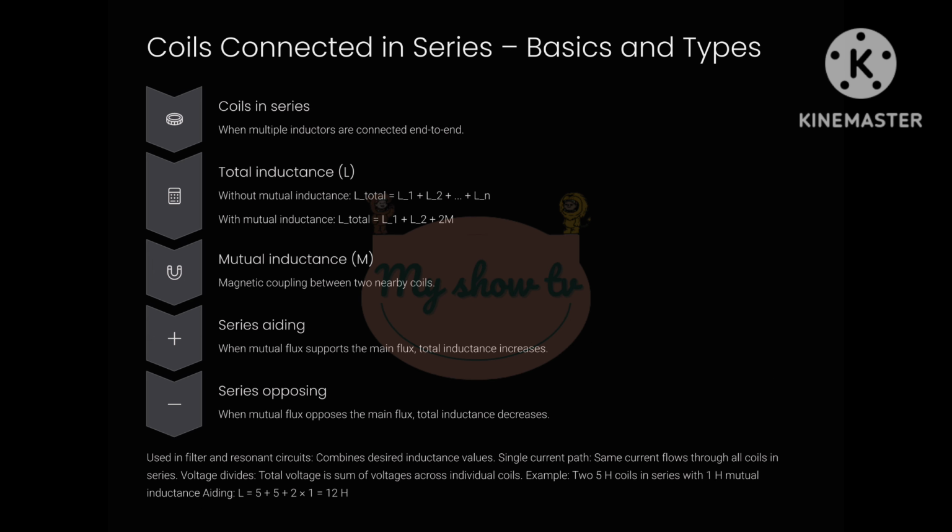Slide 3. Coils connected in series, basics and types. Now let's move to coils in series. Imagine connecting two or more inductors end to end, that's a series connection. In this setup, the same current flows through all inductors because they share a single path. The total inductance depends on whether there is mutual inductance, M, or not. 1. If there's no mutual inductance, i.e., coils are far apart, total inductance is just the sum.